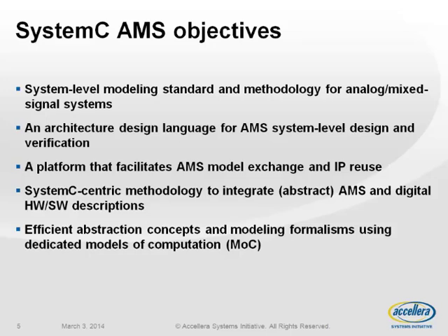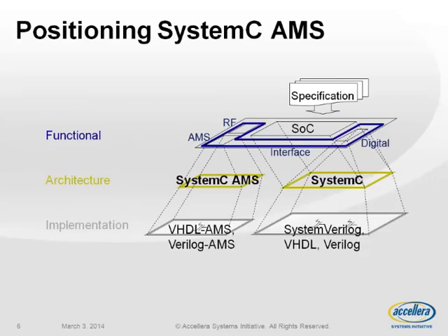We built this on SystemC, so we can facilitate seamless interoperability with known ESL design methodologies. So hardware-software descriptions you normally have with processors can now be extended with analog mixed signal extensions. And I think what we have done as well is we have made some dedicated models of computation which are very efficient at the system level. So new abstraction methods and concepts will be introduced. So if you position that in a graphical way, you see something like this, is that we have at the implementation level the known HDL languages. SystemC is more for the architecture domain and SystemC AMS complements the domain where we can do architectural design.